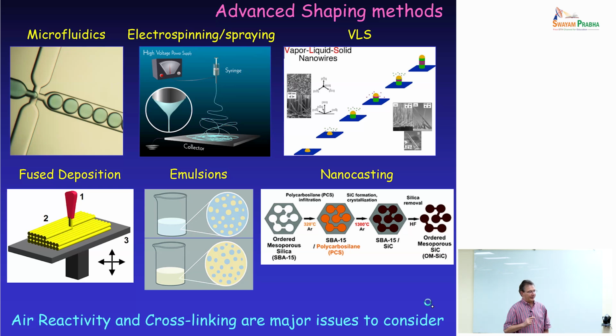If you remember, I mentioned that you can process a preceramic polymer body by mixing into the preceramic polymer some fillers, some particles, and if the particles are beyond a certain threshold in terms of their volume within the body, then they would form a self-sustained structure that avoids the melting of the material.